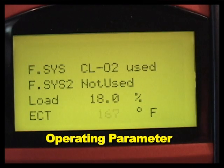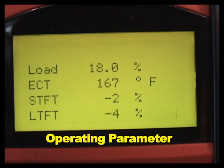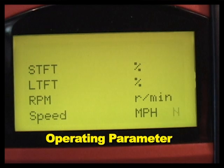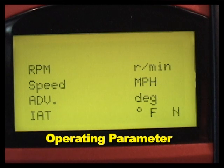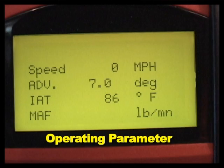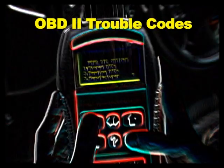An operating parameter is an acceptable minimum and maximum electrical value. It might be an acceptable voltage range from the oxygen sensor, a resistance range from a temperature sensor, or an acceptable current draw from a fuel injector coil winding. In any case, the computer knows the limits for most input and output levels in its memory chips.